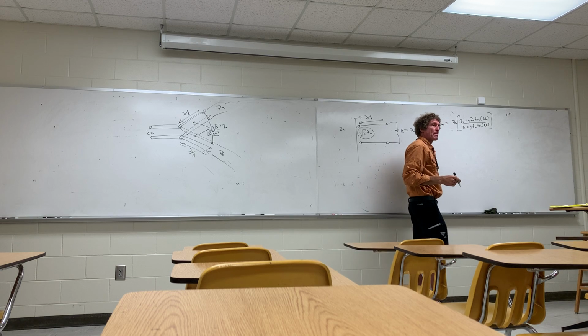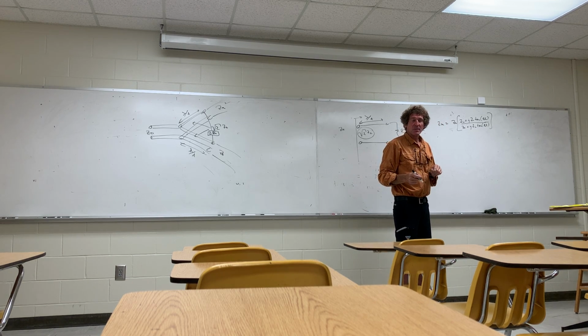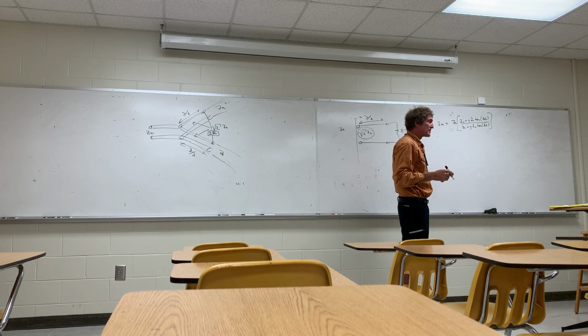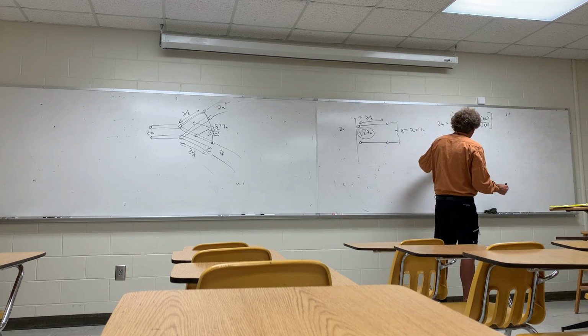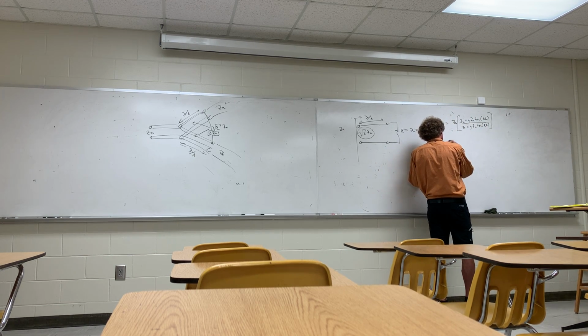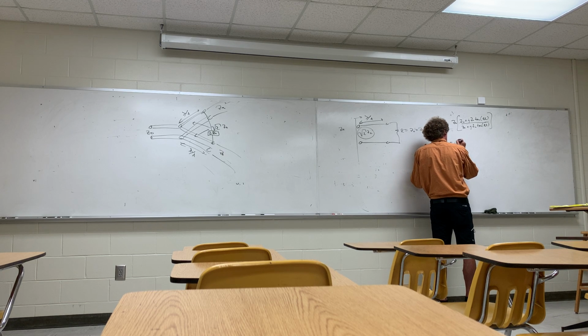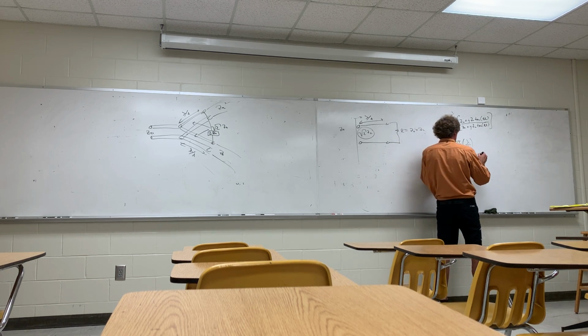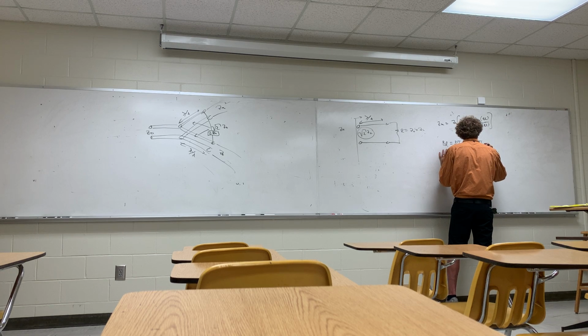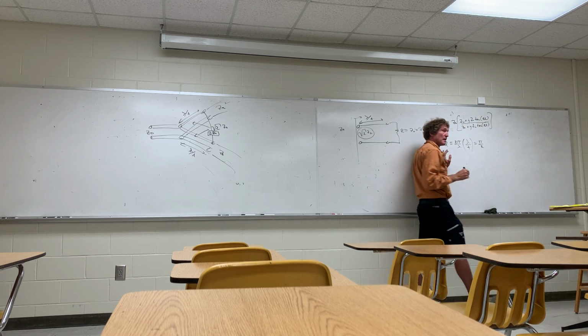Y'all remember that? Okay, now, first thing, when I look at this quantity beta L, well, beta is 2 pi over lambda, and the length of our lines are lambda over 4, right? So my beta L becomes pi over 2, right?